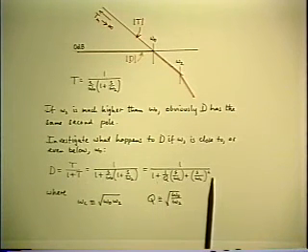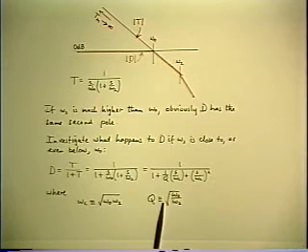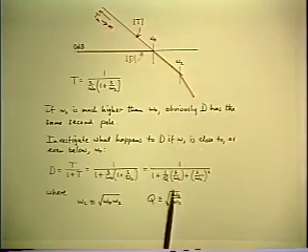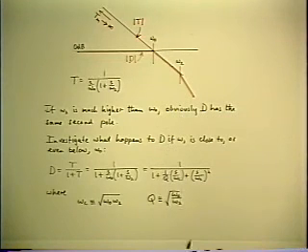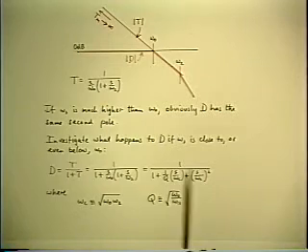But now we already know about all the possible shapes of the quadratic relative to the value of Q. So we want to see what value Q can take. And since the omega 0 is being kept fixed and the omega 2 is a parameter that's variable, it can have any value, so Q can have any value. So what we need to do is to look into the various possibilities, represented by a typical case for each of the useful ranges of Q, namely high Q and low Q. And maybe one in between, depending on whether Q equals 1 is important or Q equals 0.5 is important. So let's look at the useful cases.